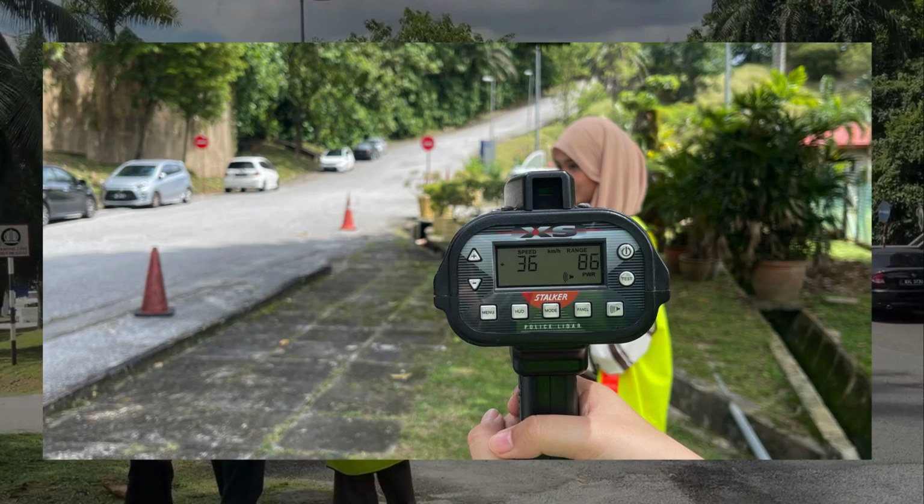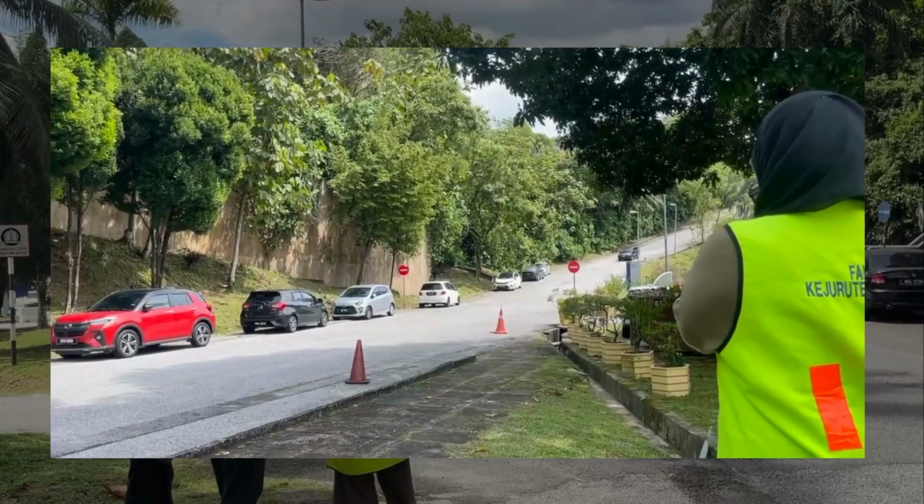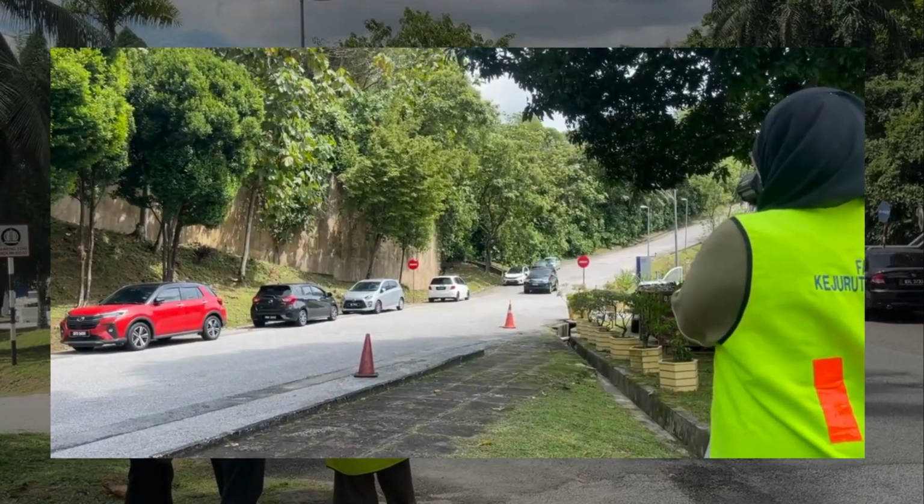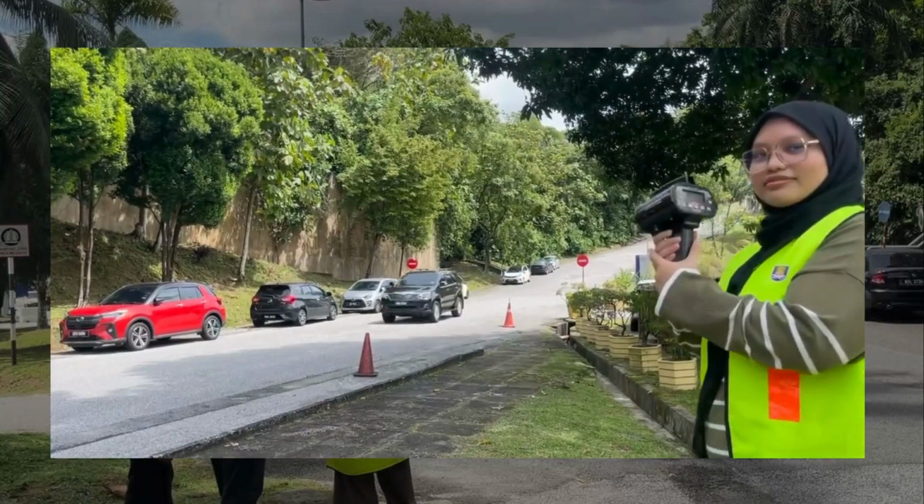To conduct a spot speed study, first, the radar gun is switched on. Then, the operator aims the radar gun at approaching vehicles to ensure proper alignment for accurate readings. Then, the vehicle speed data is recorded when the beep sound is heard.